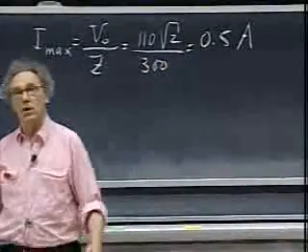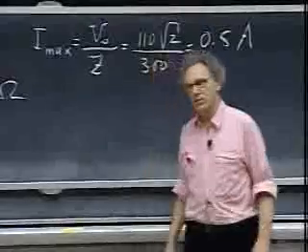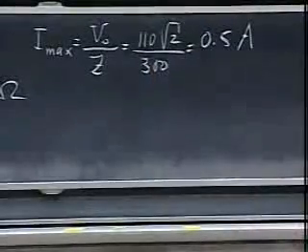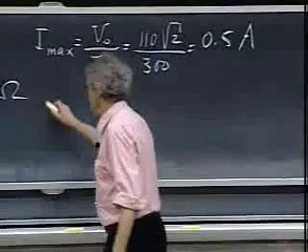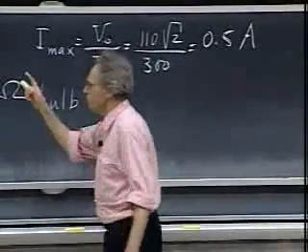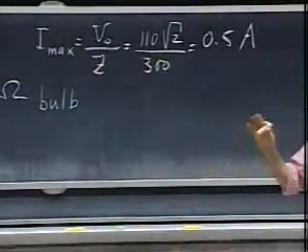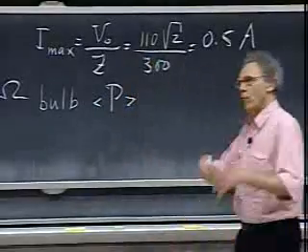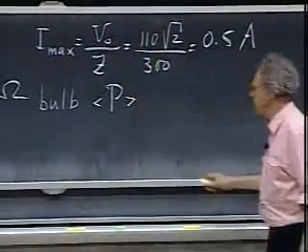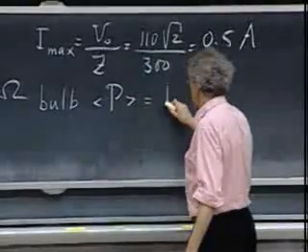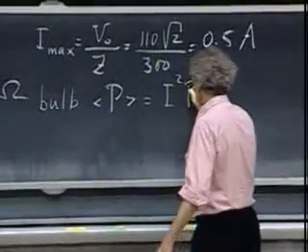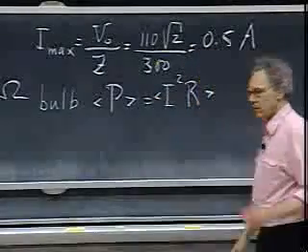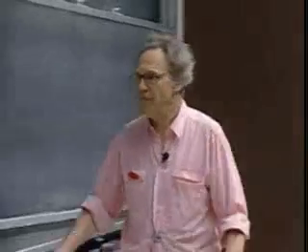And now I can tell you how much power is dissipated in the light bulb, which is I squared R. The light bulb is the only component which has a resistance. Well, maybe the L has also a little bit of resistance, but we will ignore that for now. So in the light bulb, the average power over one full cycle of my oscillations equals the time average of I squared R. The time average value of cosine omega t squared is always 1/2.